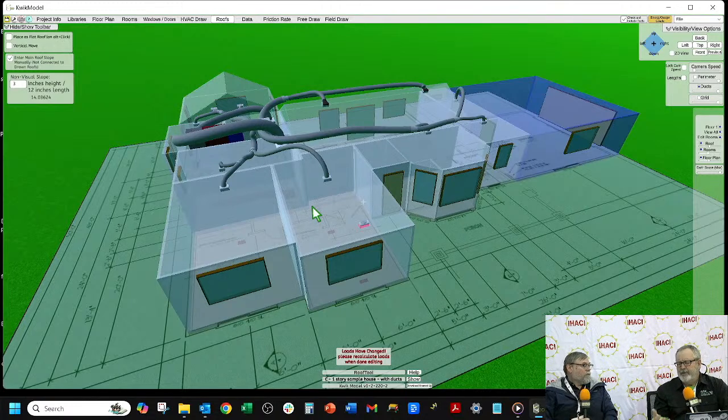And Manual J is notoriously considered to be safe. It's higher than what the real loads of the house are. There's a lot of worst case scenarios built into it. So the chance that your house will ever actually need what Manual J says in the wintertime is pretty slim. And so your heat pump's going to work fine. On those really cold nights, if it's going to run off electric strips, put in a plug-in heater. That's an electric strip.